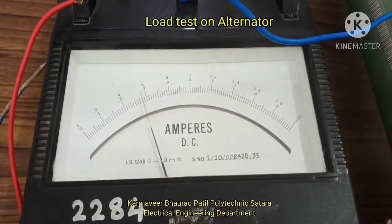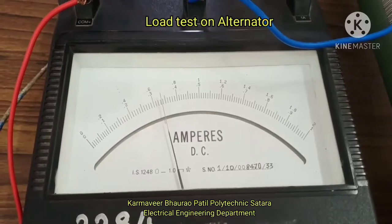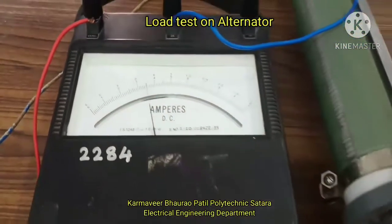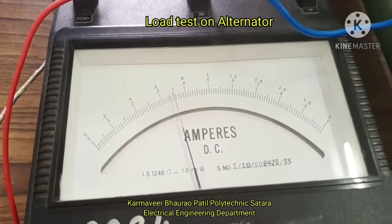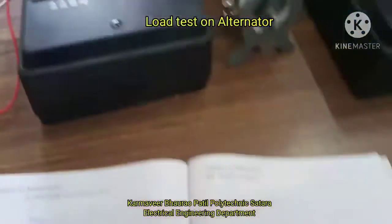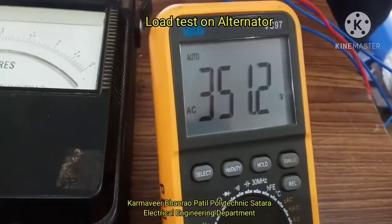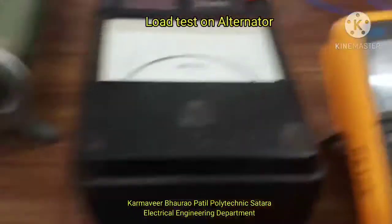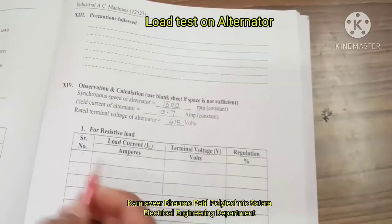Increase the current till the time it shows the voltage of 350. So how much is the current? Actually we have connected 2 ampere range, so current is 0.7 ampere. Field excitation current is 0.7 ampere and the output voltage is 350. So this is your first reading.